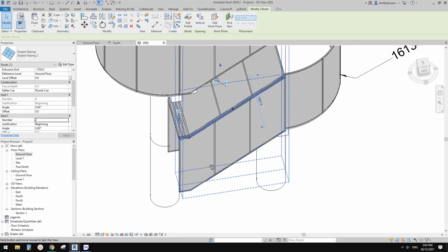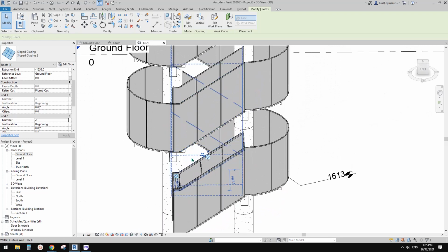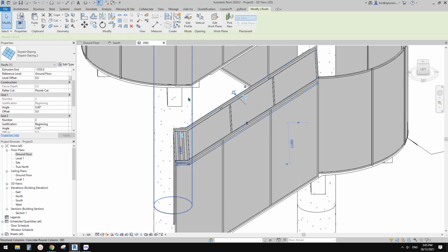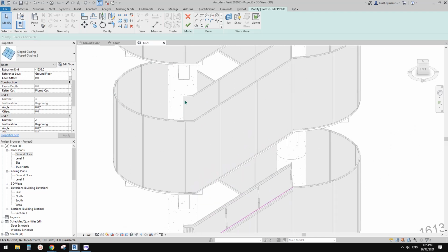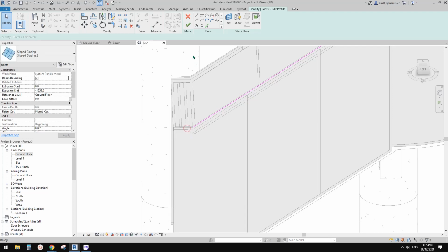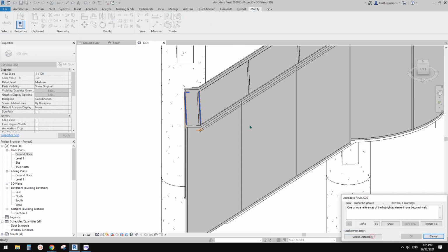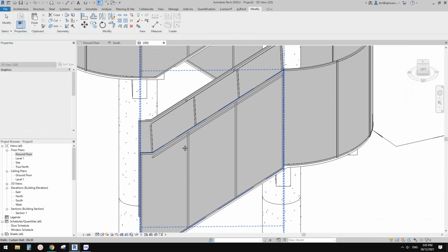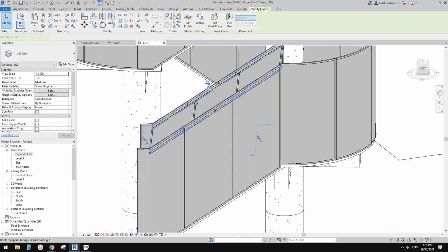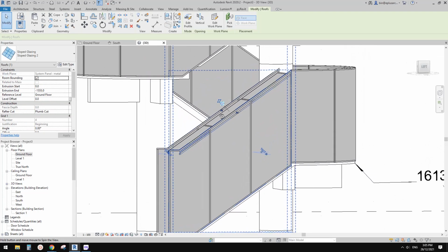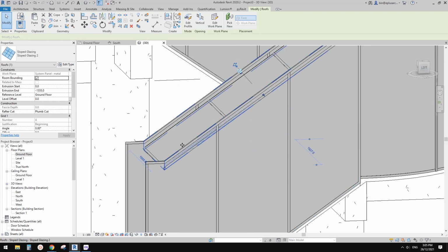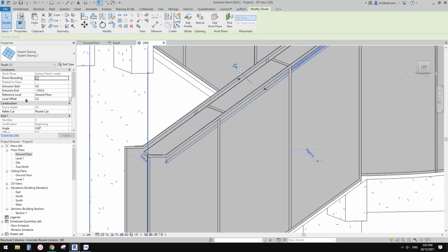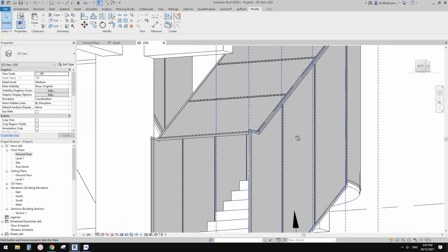I think we need to just break this part, because we are going to create this as part of this. So now I'll delete this, finish this, and delete element and delete instance. So now we have this one. It looks like it's not matching here, and also there's a little offset from the top. Maybe we can just level offset, typing a number. Yeah, I think that's better.